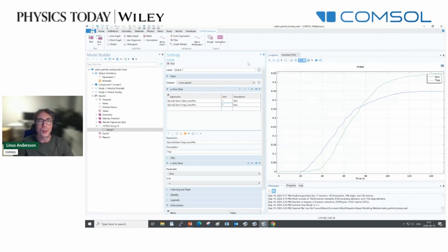What about the accuracy of this model? Is it any accurate at all? No, it's not, because I personally decided which equations to use. I made up the parameter values, and I'm not a mosquito scientist. But that aside, if we're talking about the purely mathematical error sources here, there's first of all going to be a small numerical error in the velocity potential because of the mesh. And that error is quite controllable. We can just refine the mesh a little bit and see how the results change. Spoiler, not much. The mesh is fine enough already.